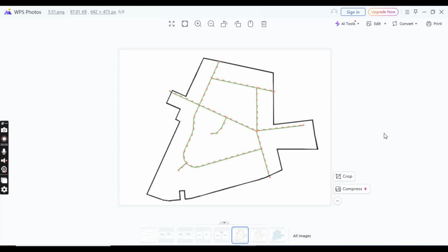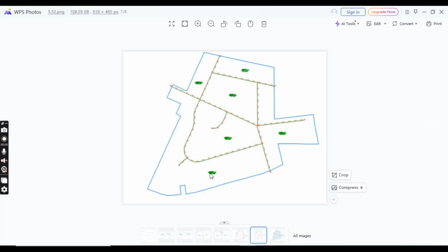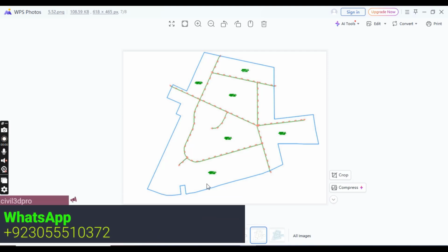Parcels form to fill the spaces contained by the original outer boundary. You should always begin a parcel subdivision project with an outer boundary of some sort, like this figure. You can then move road centerline alignments to the side, which divides the outer boundary parcel, like this figure. It's important to note that the boundary parcel no longer exists intact.